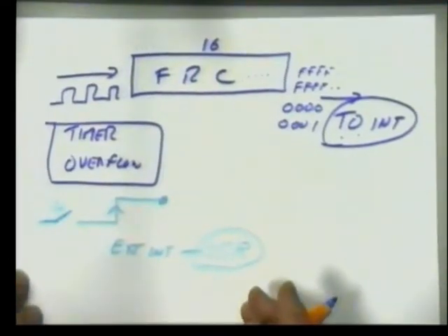An alternative is to use a wonderful concept known as input capture. What input capture means is we still issue the interrupt in the normal way, but we take a snapshot, a copy of the free running timer at the event it occurred. You don't need to do this in your program, it happens automatically.